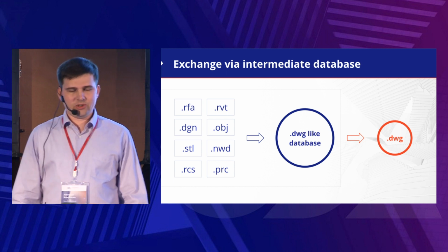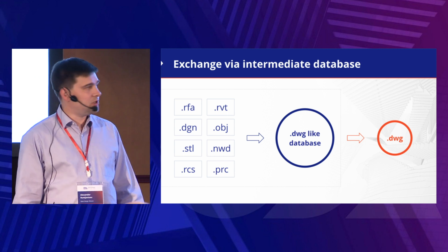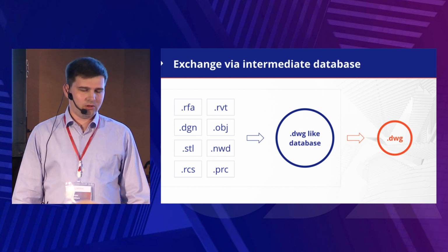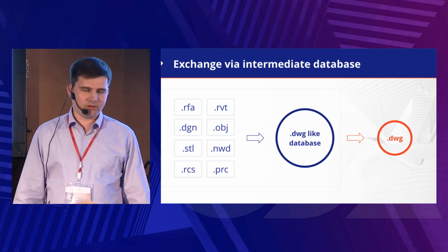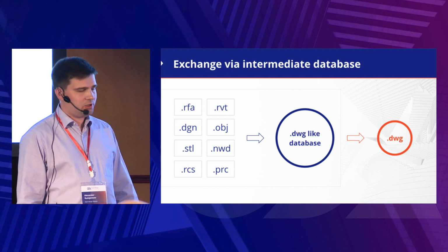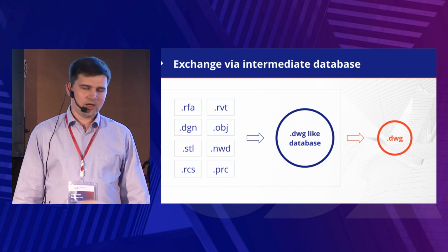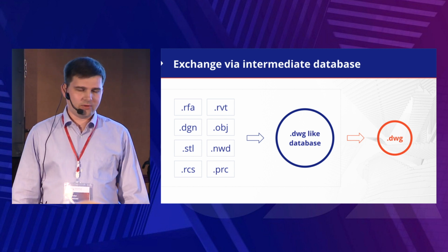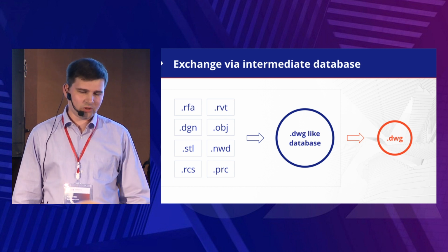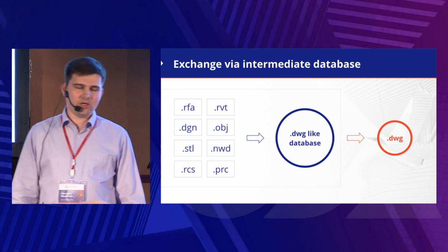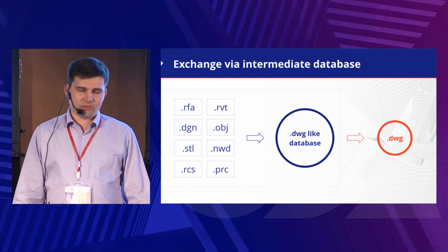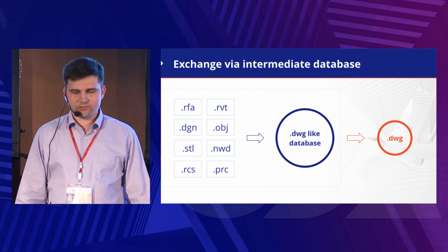The good bonus of this scheme is that Visualize SDK already has this part of the functionality inside. So by using visualization, we are able to convert all ODA supported formats into the intermediate database. The only step which should be implemented is conversion of this visualized representation into DWG format.